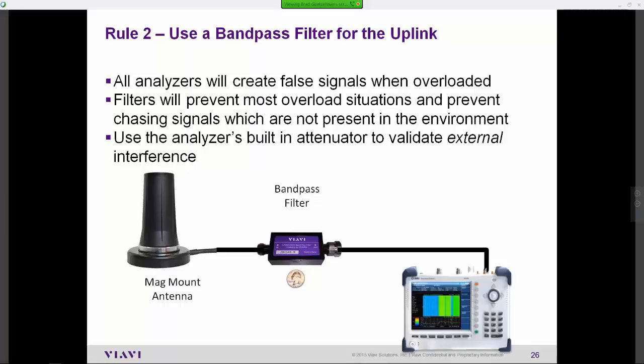Our instrument and every other manufacturer's RF test set will have some type of radiated emissions. By being able to move the antenna away from these electronic sources, you can often see that what appears to be external RF is in fact being generated locally by whatever power supply, laptop, or vehicle you may be in. By moving the antenna and seeing those correlating changes, you can often isolate that, yes, you may have radiated emissions showing up on your spectrum analyzer, but they are in fact not affecting your base station, only your display.